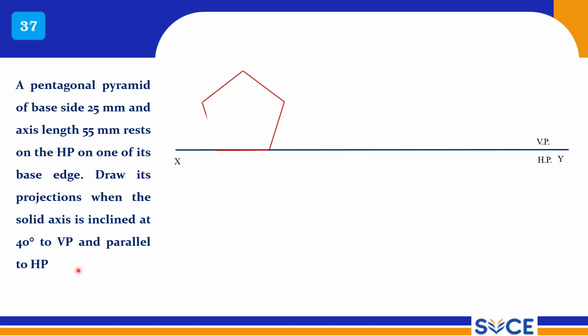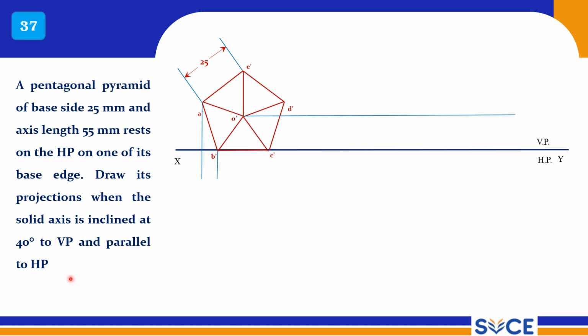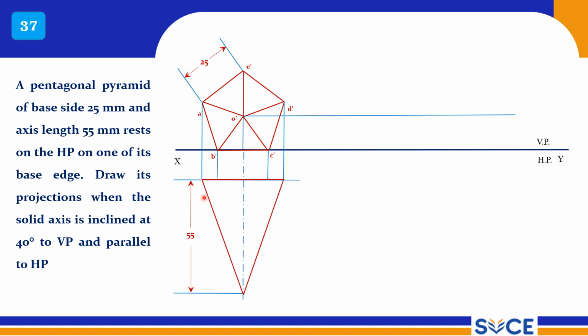So draw the pentagon. It is a pentagonal pyramid. In the earlier case we saw a pentagonal prism. So draw the pentagon, and here it is a pyramid. You are supposed to draw thick lines here. It is just a pyramid, and you can get the pyramid's top view here. It is an isosceles triangle, and draw the invisible edges, that is OB and OC are invisible edges.